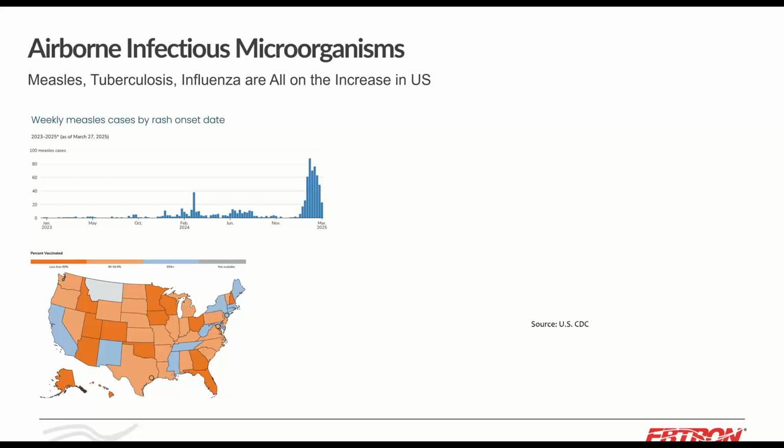Measles is one of these things that can stay in the air well after the people who had the measles left the space. And it's one thing I don't like about ASHRAE 62, for the purposes of energy, it allows you to shut off the damper to a space and shut off the ventilation to a space when it's unoccupied, even during occupied periods. I think we should be ventilating all the time during occupied periods, just in case someone left something behind.